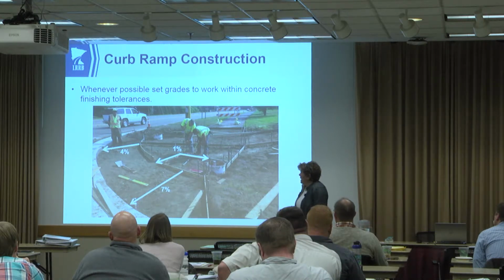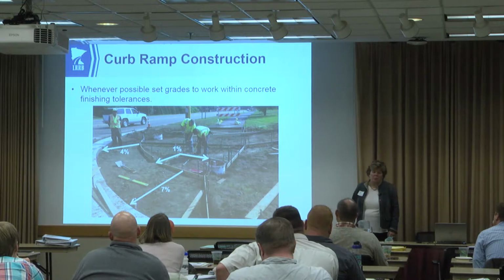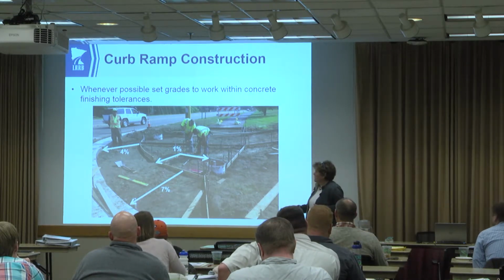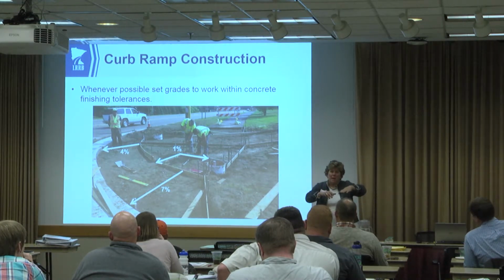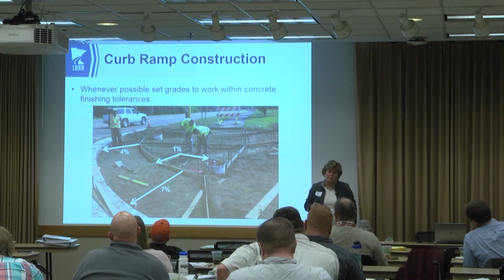Remembering that what the contractor lays out is great as long as he doesn't exceed tolerances in a way that impacts your cross slope. So what I said before, if he's got, let's say, a 2% maximum cross slope on a landing, but he digs out the middle, so now with a 2-foot level, it's steeper than 2%, that's a problem. He may be within the 1/4 inch tolerance, but he is not within the 2% maximum slope.